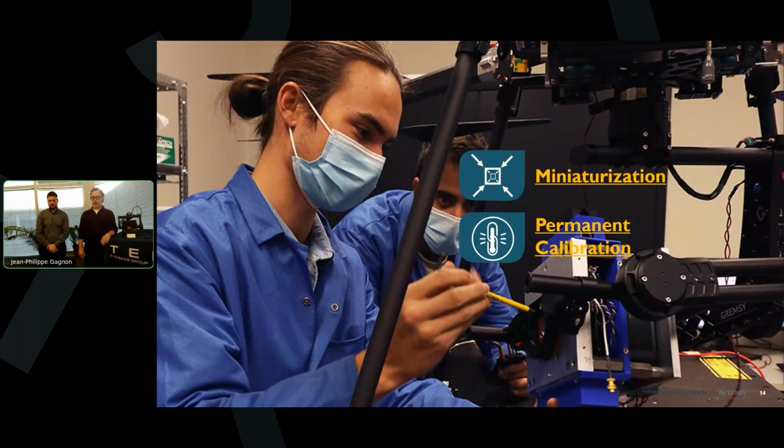Talking about the power budget, the R&D team did a good job at minimizing the power. You remember a few slides back, I talked about how we had to do a radiometric calibration to go from just the standard spectra to calibrated spectra. Normally, this is done with 2 black body measurements, a hot and a cold one. With the other members of the family, we attached black bodies at the front of the camera to do just that. But with the Nano, we couldn't do that for 2 reasons, mainly power consumption and also weight. So we had to let go of the black bodies.